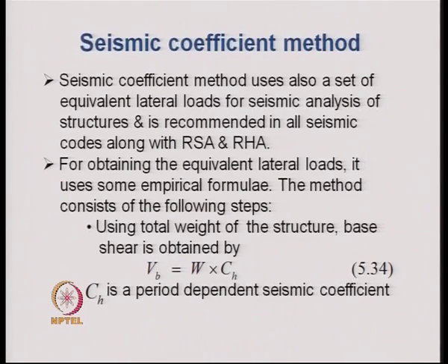Then the structure is analyzed statically to find its responses, and those responses are assumed to be equal to the maximum forces that the structure would have experienced if the same earthquake for which the response spectrum is constructed was applied to the structure. Note that the response spectrum of acceleration can also be used here in order to obtain the seismic coefficient, which we will discuss a little later.